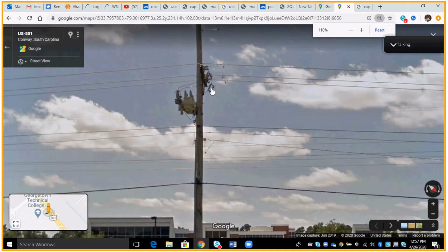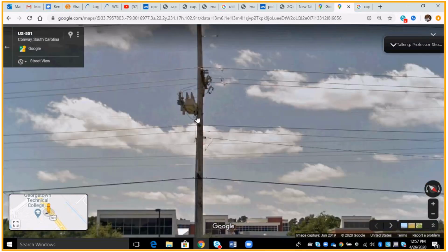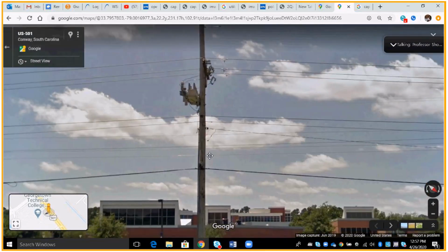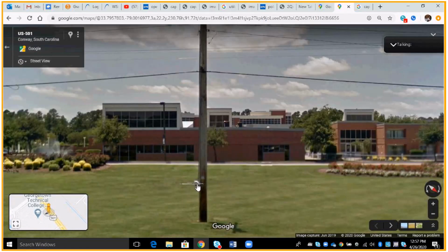Okay, switches, phases, low side riser to the vacuum bottle, bank, and you'll notice right here, wires coming down the pole. You've got an antenna, so the SCADA radio can actually reach the control box. So you got an antenna to receive the SCADA transmission, and then the control box down at the bottom. You can manually operate the bank here at the bottom, or SCADA control. Okay.